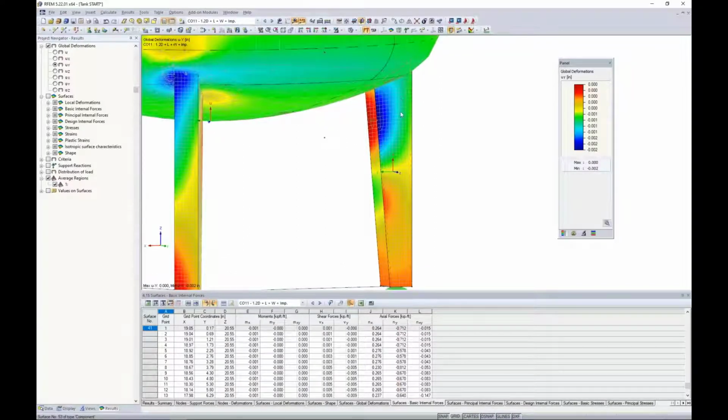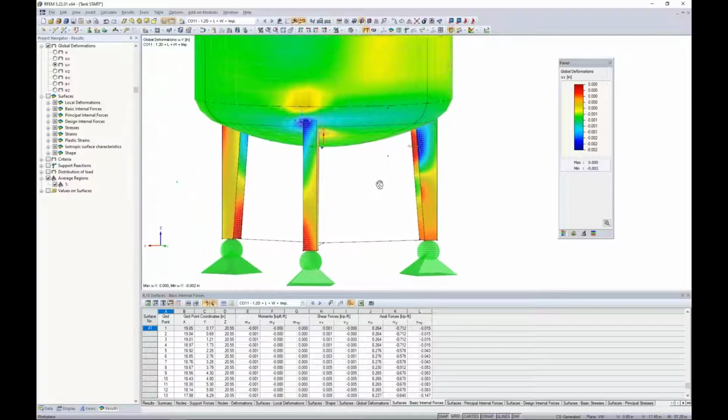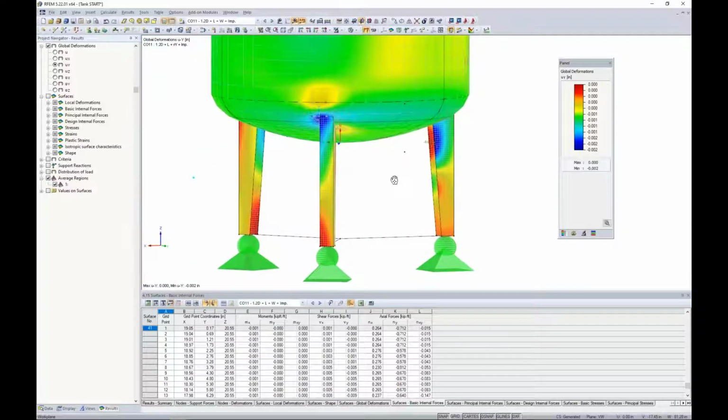We have, ever so slightly, some deflection here in the Y direction that indicates that the mesh was deformed. So possibly with a third order analysis, we could even see more of those results available to us. But this in general is just one way that we can directly model these imperfections, because not everything is going to be perfect as we're modeling here, but rather there will be errors with the manufacturing or installation process.